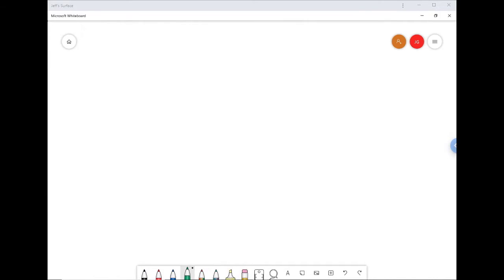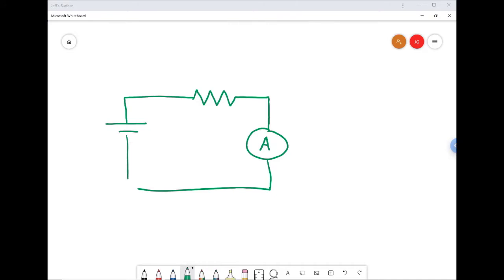So there's a power supply. That's the schematic symbol for a power supply. And it's connected to this coil of wire, which serves as a resistor. That's the schematic symbol for a resistor. And then this is hooked up to one of my multimeters, which is functioning as an ammeter, and it's in series with the resistor. And then I have another multimeter that's hooked up in parallel to the coil of wire as a voltmeter. So that's a schematic of what this circuit looks like.